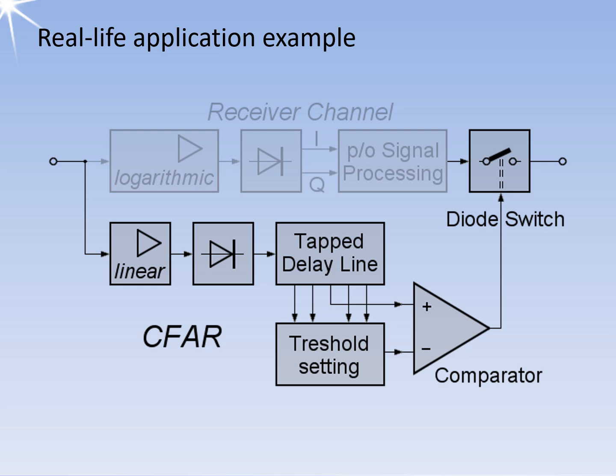In radar, the IF amplifier typically has a logarithmic amplification curve. This has the advantage that weak echo signals are better amplified, and strong echo signals are not clipped. However, for the CFAR circuit, a linear curve without separate amplitude and phase processing is preferred.